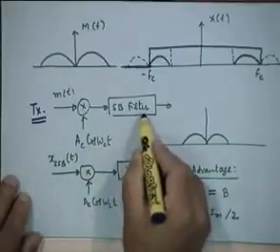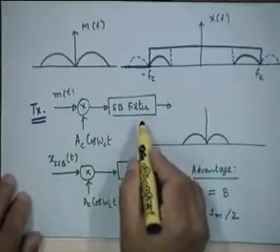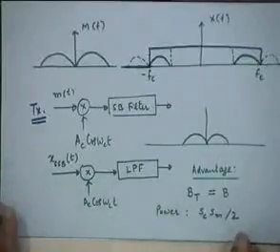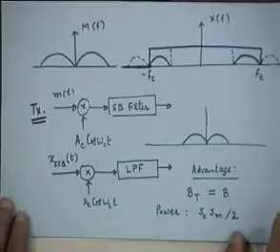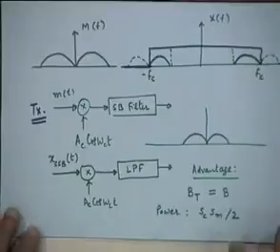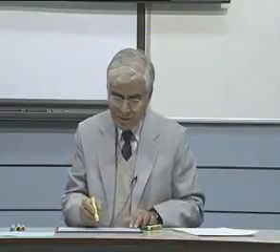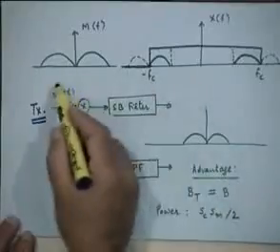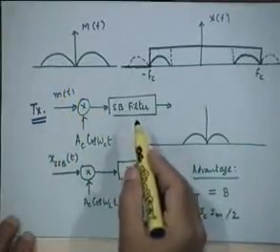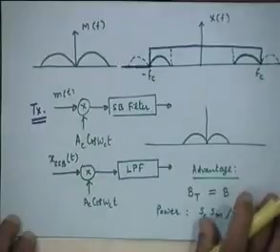We are putting the sideband filter before transmission. Please understand that. At the receiver, I am doing exactly what I was doing for the DSB-SC signal. The receiver is no longer different at all. If that was another case, then there would be no advantage. So this is the transmitter, right? So you are putting the sideband filter at the transmitter. Please understand that.